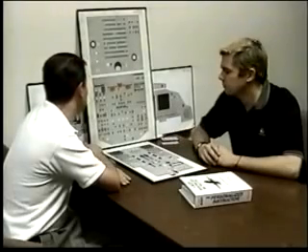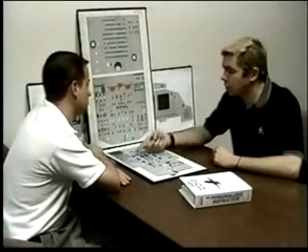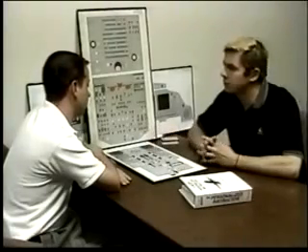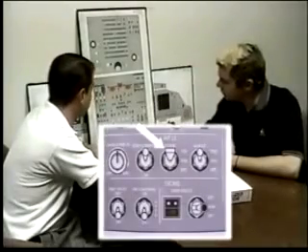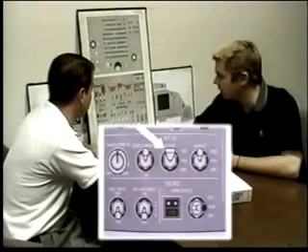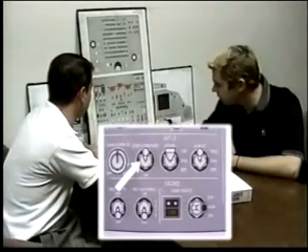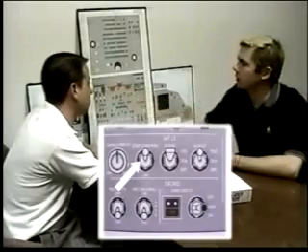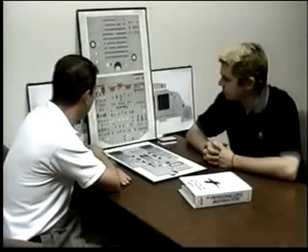What are some items that the first officer and captain also have available? They've got RMP1 and they've got ACP1 and 2. Any lights for the first officer? Sure, the first officer's got the dome light, the right dome light if the dome light switch is out of the off position. Both the crew have the standby compass light, and then the captain's got the glareshield lights. After 5 seconds, the RAT automatically deploys.